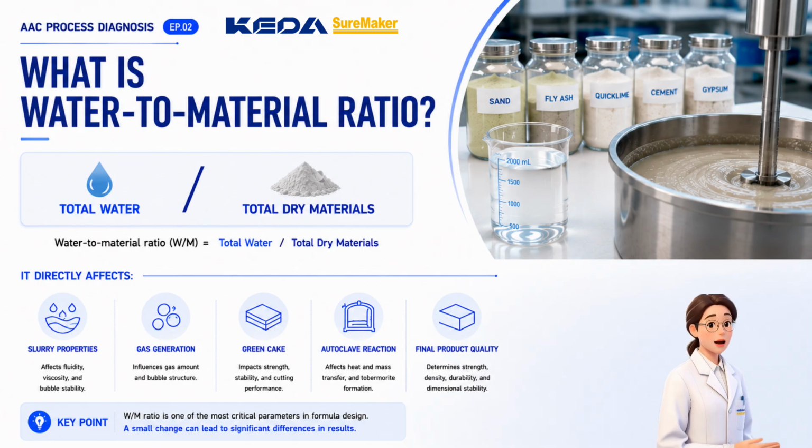The water-to-material ratio is the first key switch that determines slurry behavior. It directly affects slurry viscosity, flowability, bubble movement, large pore retention and distribution, pre-curing time, and final product issues such as watermarks and undercured areas. Generally speaking, sand-based AAC is less sensitive to the water-to-material ratio. If it is not close to the critical range, the impact is usually not obvious, unless the sand slurry is too fine or has low water absorption. Fly ash-based AAC is more sensitive to the water-to-material ratio. Once it exceeds the critical range, it may easily cause thickening with trapped gas, or settlement and collapse.